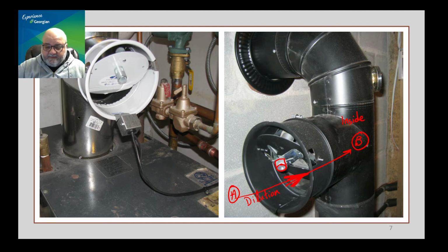And secondly, if for any reason there is a downdraft, which also results in the flue gases coming back down instead of going back up, you want those gases to be spilled in the room surrounding the appliance, as opposed to falling in the combustion chamber and creating a huge hazard. So that's generally what we do with the barometric damper.